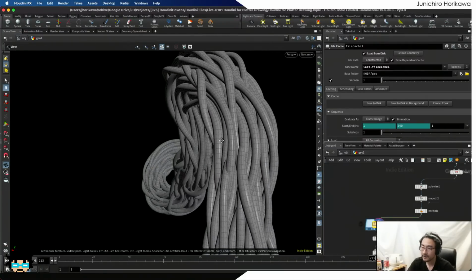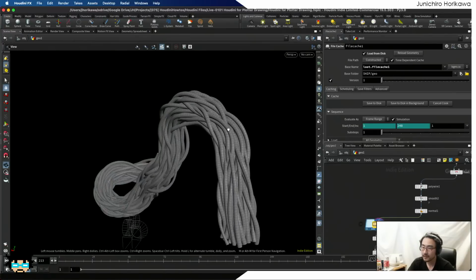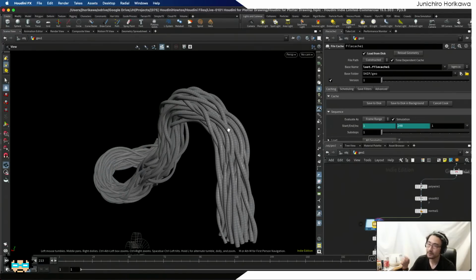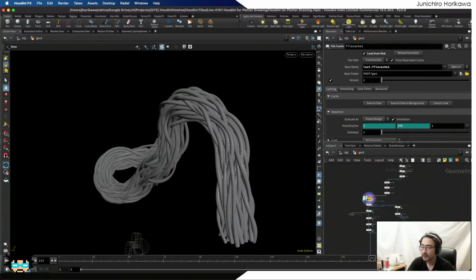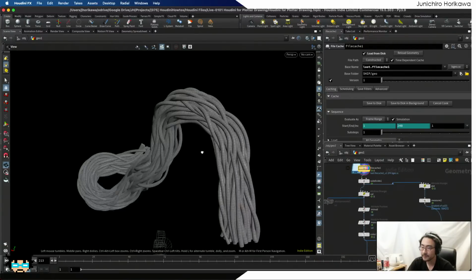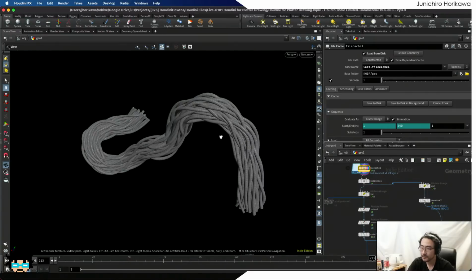Now there are many ways to convert this into a drawing, like you can create a hatching, or you can plot a number of points on top of the geometry to use for a drawing. But the simplest, easiest way to create line drawings for the plotter machine is to create a contour. So I'm going to show you how you can create a 2D contour out of this geometry